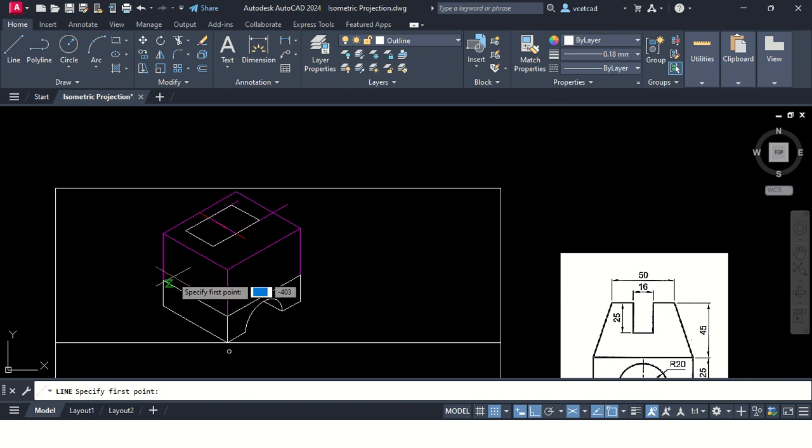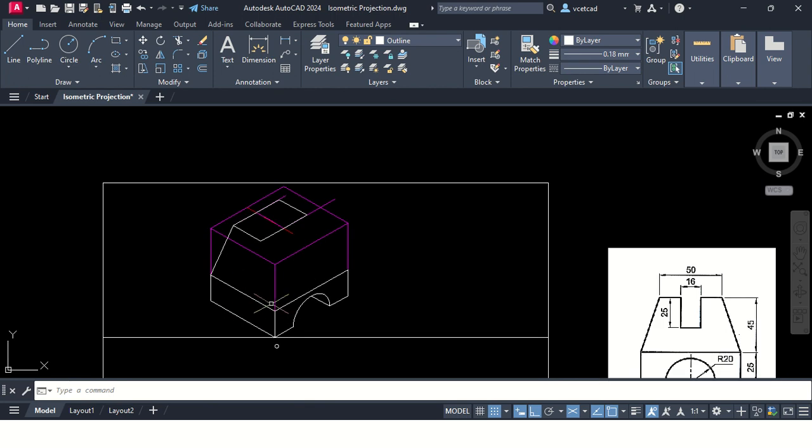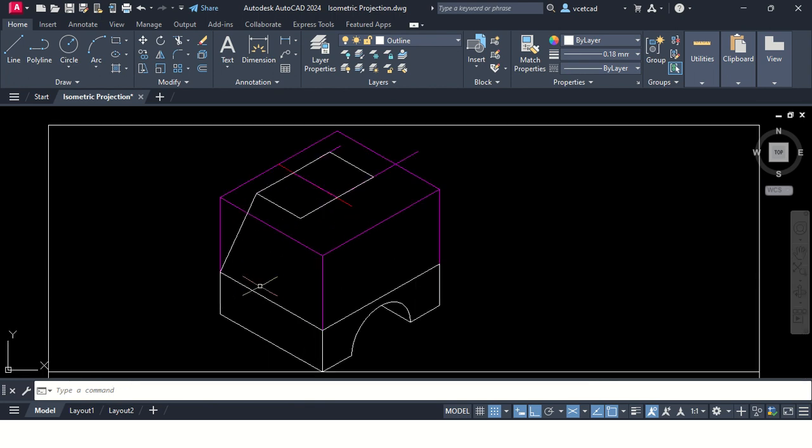Now let us connect with the bottom portion. So here we can connect directly. So this is that inclined portion. Now on this side also we need to connect. So how to do that? For that, L enter from this point. How much is the distance? 50 millimeter is the base. So you will get a point, and from that point you will connect it.